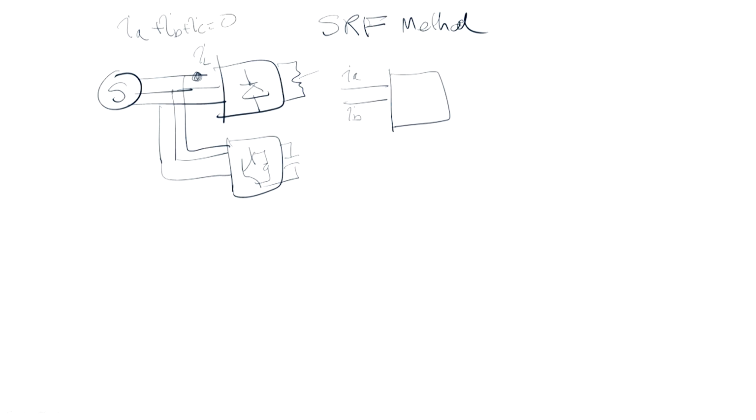So, you can generate the Ic, or if you have a 4-wire system, then you require to sense another current. I am considering a 3-phase 3-wire system. So, essentially what you will do, you will first convert from ABC to the alpha beta frame. So, that is the Clarke transformation. So, you have then I alpha and I beta.